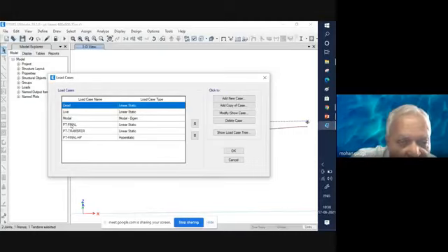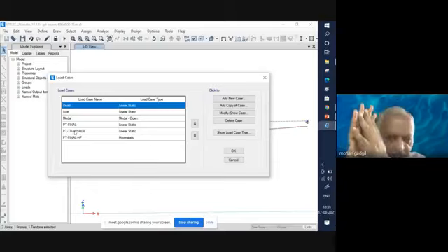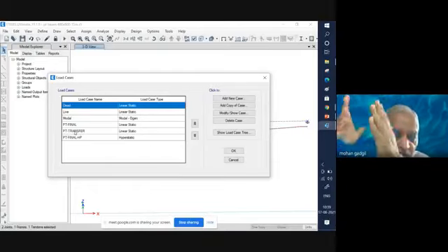So there are 3 different cases which are built into ETABS itself: PT transfer, PT final, and PT final plus the hyperstatic forces. Now PT transfer is the state at which you have the beam with only its own weight, and you are applying the pre-stress, because live load will come later when the beam is placed in operation.